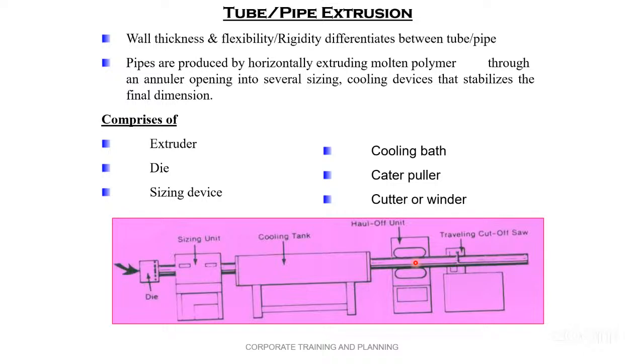Now finally, again there are 3 to 4 pieces of equipment also there. The size of the pipe, the diameter of the pipe. Therefore, there may be a beta gauge here, which will give the final thickness and the diameter of the pipe. After the beta gauge, there may be a corona treatment given to the pipe.